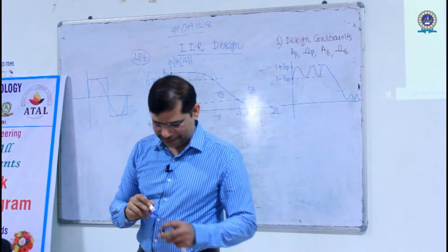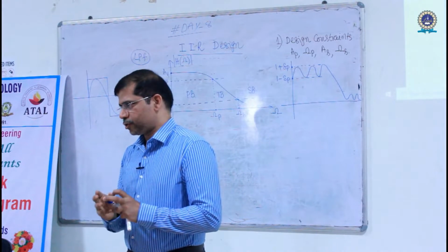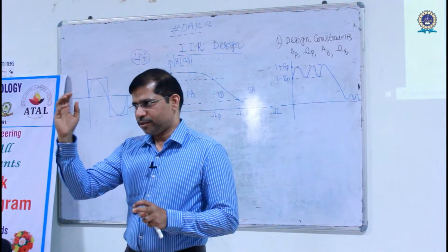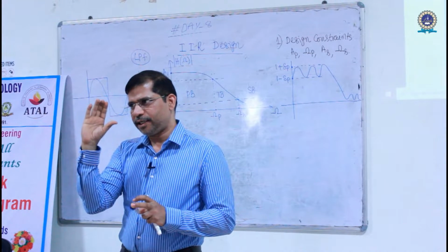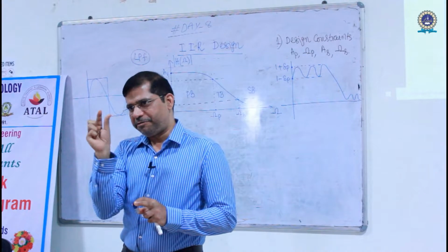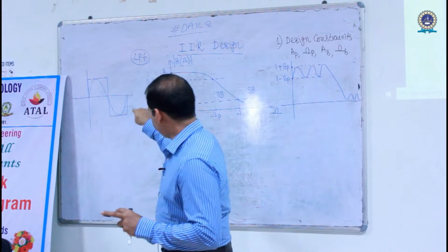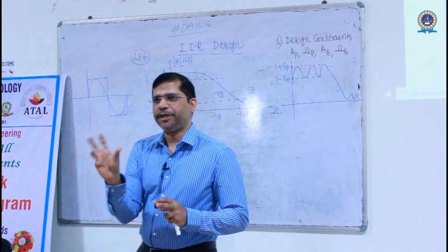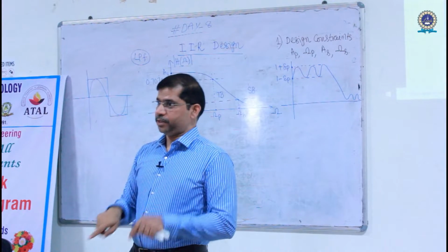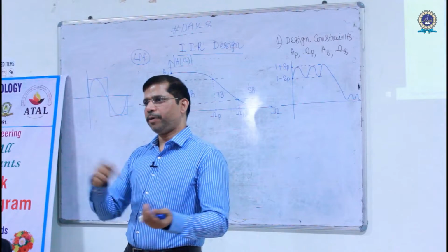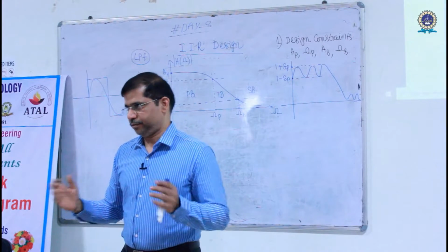No. Why not? I will say yes, because you always need to calculate the error between the square waveform and the sinusoidal waveform. If you consider this particular one, the error will be some 20 to 25%. So if your system allows 25% error, then you can replace the square waveform with a sinusoidal waveform. You have to ask yourself, can I allow this much error?